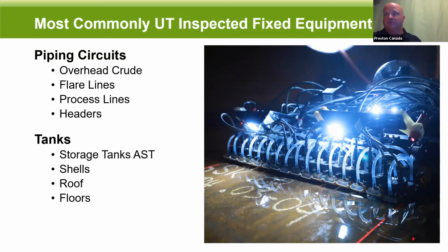But AUT cost is pretty high, and access, you have to get directly at it, and the speed of it is pretty slow. Well, RUG is a very fast system. The system can take millions of readings and cover large surface areas in single shifts. So anything that is not just a small, narrow, focused job with access that you're willing to do off scaffolding or something along those lines that costs money as well, you should really look at RUG. That'd be the better option for most inspection cases. They both get you a very high confidence score in RBI.